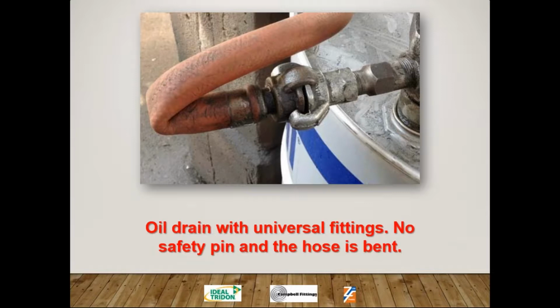And typically, you're not going to see a lot of pins. Usually they're along the ground, or in a drawer in the storeroom, or in someone's pocket just in case there's an inspection. They don't really have these pins in the hoses. In fact, I've only seen pins in a Chicago universal fitting once, and I was stunned, and I asked why, and they basically said, oh, we got fined last month. So that's when you'll find pins.